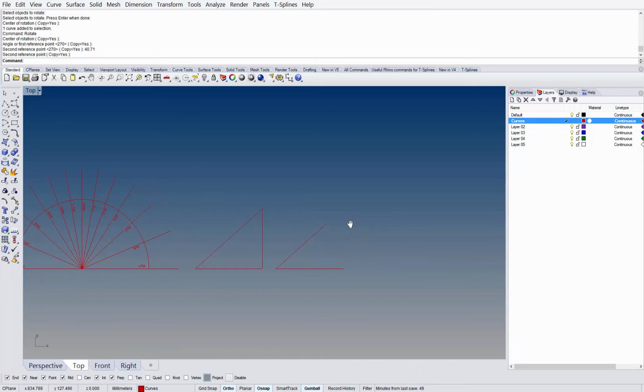And what I'm going to do is I'm going to draw using this. I'm going to draw a straight line going up, way past it, and then I'm going to type extend, and then I'm going to click this line, spacebar, and then this line.